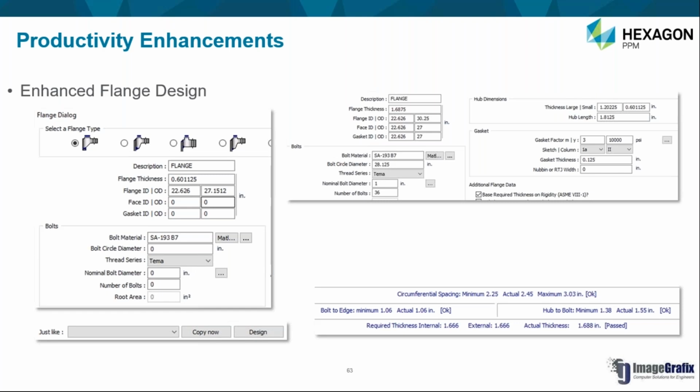Then PVL will quickly rough out a flange design, and based on that, you can very well optimize it if you want to. This is really a very quick way of roughing out the body flange design. So just by entering the M and Y value and clicking on the design button, the software will give you a rough flange design, and then you can optimize it.